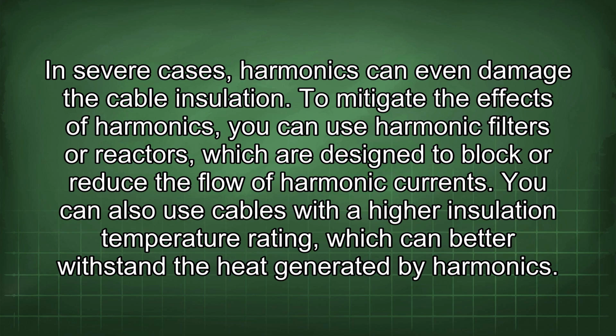To mitigate the effects of harmonics, you can use harmonic filters or reactors, which are designed to block or reduce the flow of harmonic currents. You can also use cables with a higher insulation temperature rating, which can better withstand the heat generated by harmonics.